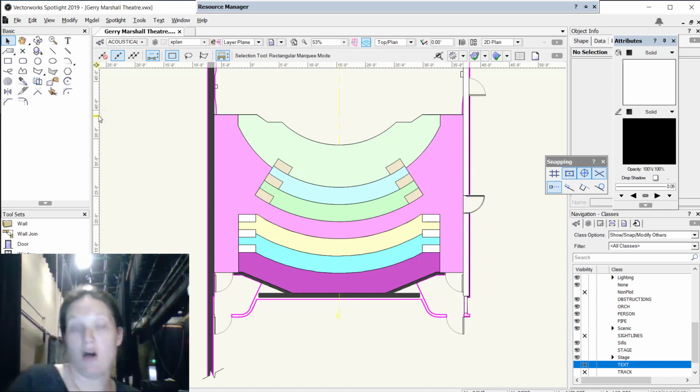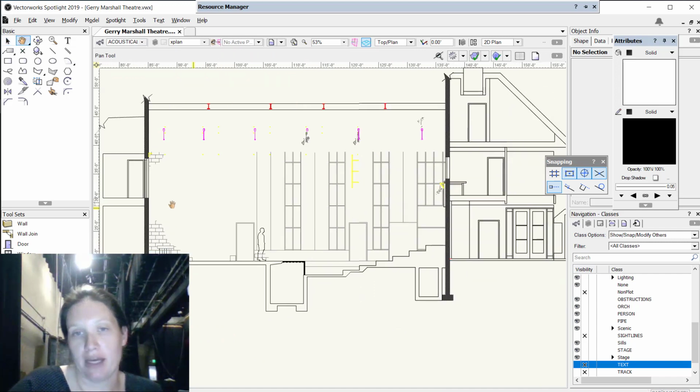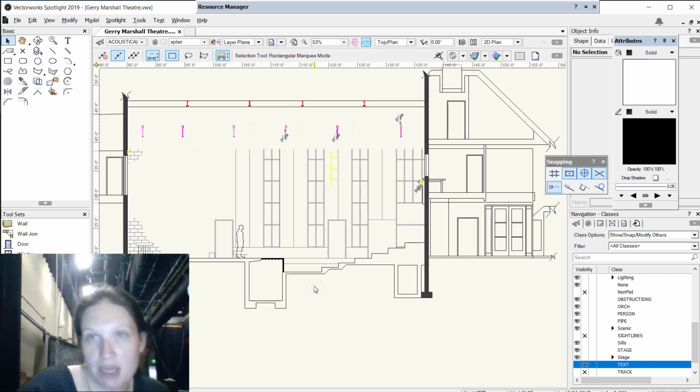So once you've done all of those shapes, then you'll use your section view and figure out what height each of these should be, okay? And you'll come over here and you'll be like, okay, so this first step relative to 0, 0 being the ground floor, the top of the stage deck. So that first piece is going to be minus 2'6", and then you would extrude it below that space. That would be its initial starting Z height, minus 2'6". Then you'd extrude it below that height, and then you're going to measure each of these intermediate step heights.